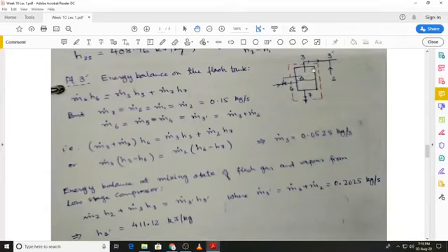So we again can come back to the solution, and now you can see that I've shown that over here, and that is equal to m dot 3 prime, because m dot 3 and m dot 2, when they are added together, that is the total mass flow rate that is compressed by the high stage compressor. So m dot 3 prime is equal to m dot 3 plus m dot 2, and we substitute this value, that is, instead of m dot 6 we have m dot 3 plus m dot 2, and then we rearrange this expression.